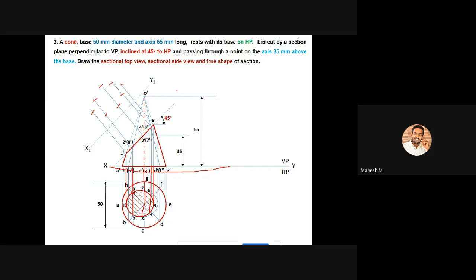Okay, so please remember one thing. The cutting point should be marked at the same place. That means if you are measuring the distance from the reference line towards point number 1, then you have to create that particular arc from point number 1, because this one is the vertical line from point number 1. So you have to create only the arc at this place.